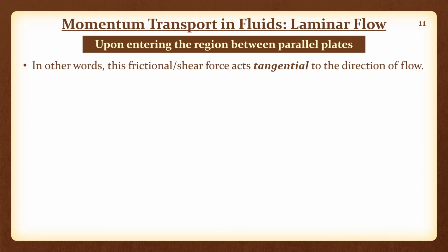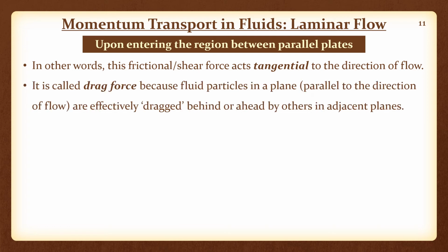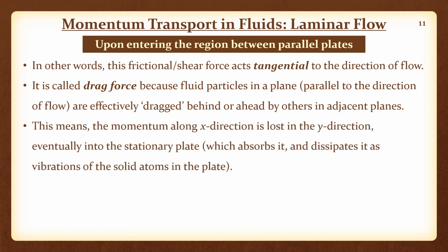So, in other words, this frictional force, which as I just said is the rate of transport of x momentum in the y direction, acts tangential or perpendicular to the direction of flow. It is also called a drag force because fluid particles in one plane, which is any plane parallel to the direction of flow, are effectively either dragged behind or dragged ahead by the fluid particles in adjacent planes. Once again, to reiterate, this basically means the momentum along the x direction is lost in the y direction, eventually into the stationary plate.